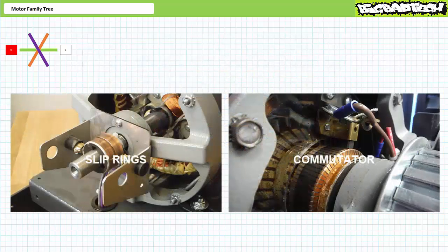You recall the slip rings found on synchronous and wound rotor induction motor rotors were continuously conductive rings that maintain electrical contact between a stationary connection and rotating rotor winding regardless of rotational position. A commutator is plainly divided and includes conductive and non-conductive sections such that only selective portions of the armature windings are energized at any particular time depending upon rotational position. DC electricity is routed through the armature winding of choice via a pair of brushes. As the armature rotates, the commutator breaks one connection and establishes another.